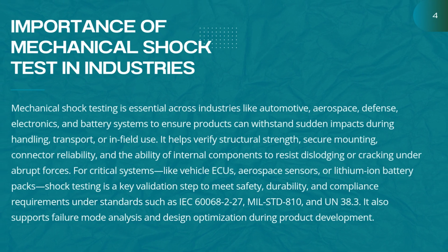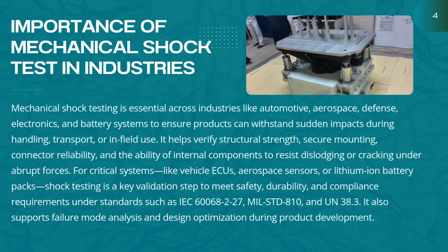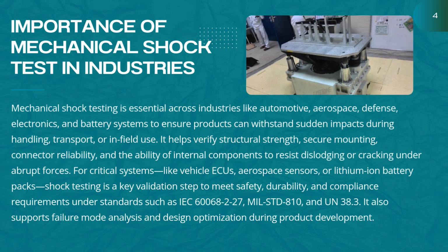Importance of mechanical shock test in industries. Mechanical shock testing checks if products can survive sudden impacts like drops or jolts during handling or real-world use. It's critical in sectors like automotive, aerospace, defense, and battery systems to ensure strength, safety, and compliance with standards like IEC 60068-2-27, MIL Standard 810, and UN 38.3.